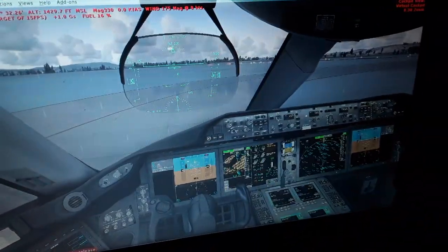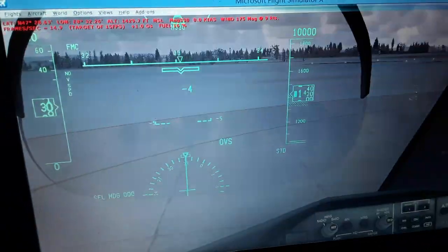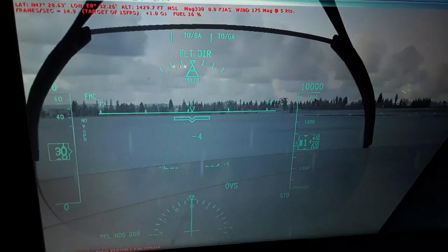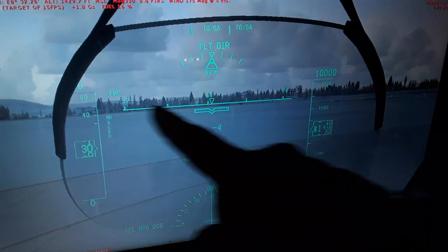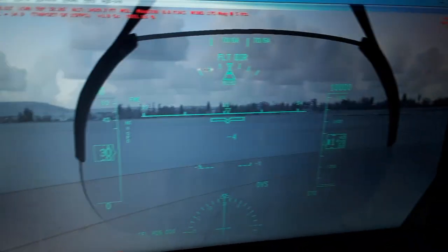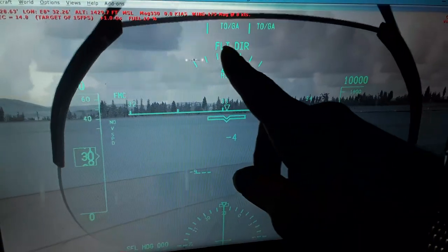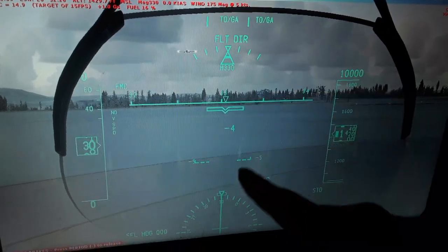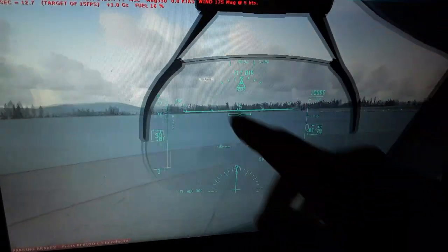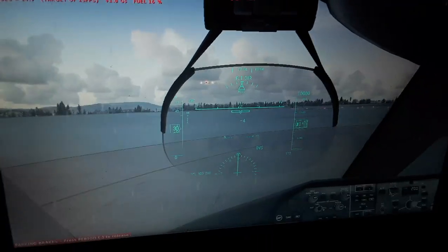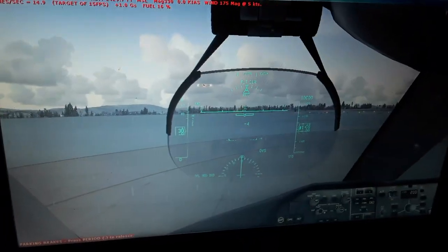So we can see also the same information here in the head-up display. When we fly, you can see the airspeed indicated, the barometric altitude, the airspeed selected, and the altitude selected from the autopilot. The flight director, takeoff, go around here also. The HSI, horizontal situation indicator. So you can see now here we have an incoming aircraft, a Boeing 737 for landing.